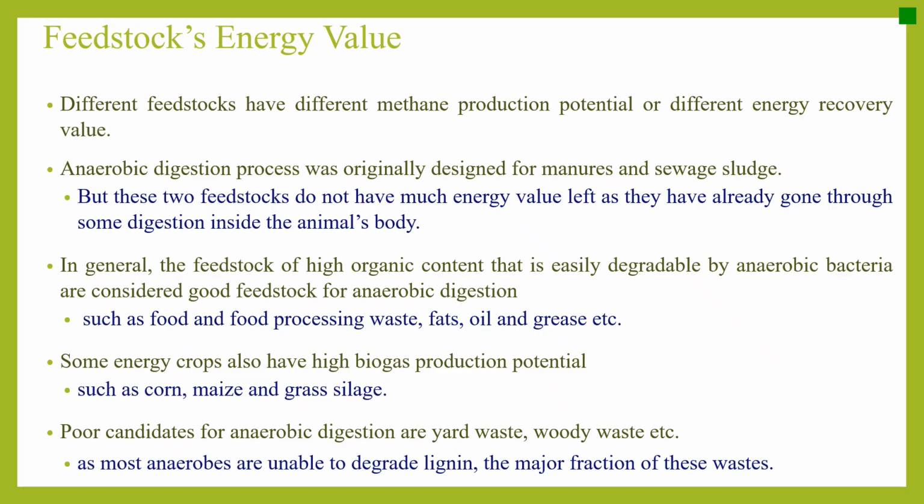Feedstocks energy value. Different feedstocks have different methane production potential or different energy recovery value. The anaerobic digestion process was originally designed for manures and sewage sludge, but those two feedstocks do not have much energy value left as they have already gone through some digestion inside the animal's body.